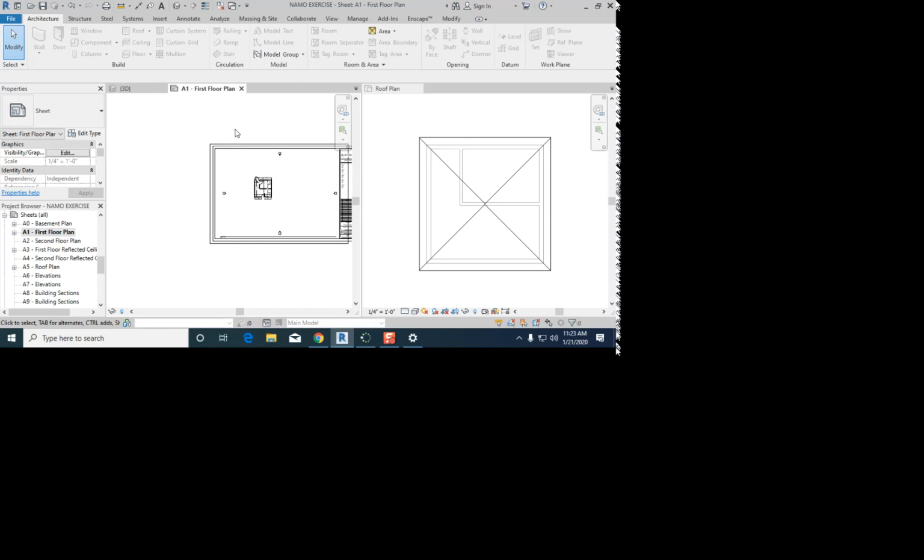Perfect, okay. When you open up a new Revit project, what should you consider? What type of space it is? Residential or... Perfect, yep, so that would be referred to as your template. Good. Template is one. What else? Yep, so the construction. What does the construction mean? The wall. And so if you don't know if it's a 2x4 or a CMU wall, is that okay? Yeah, you could even just consider that, okay, we're going to start generic. Okay, let's stay with walls for a minute. So we talked about the construction. When we draw the walls, what do we also have to consider?